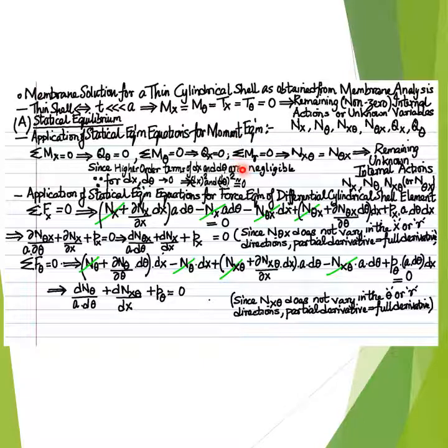The application of the third statical moment equilibrium equation, sigma mr equal to 0, that is the statical moment equilibrium equation for moment equilibrium about the radial or r-axis, results in an equality between the in-plane or membrane shear forces nx theta and n theta x.